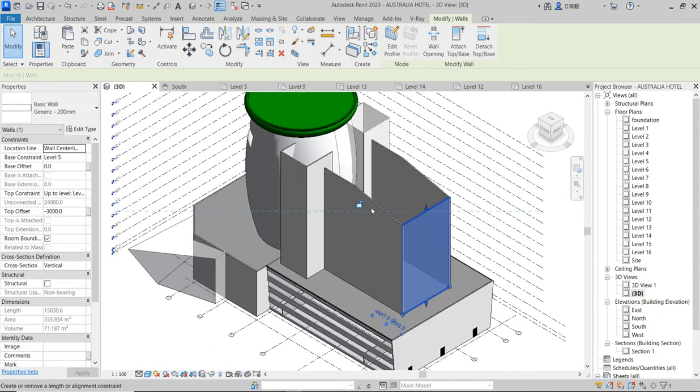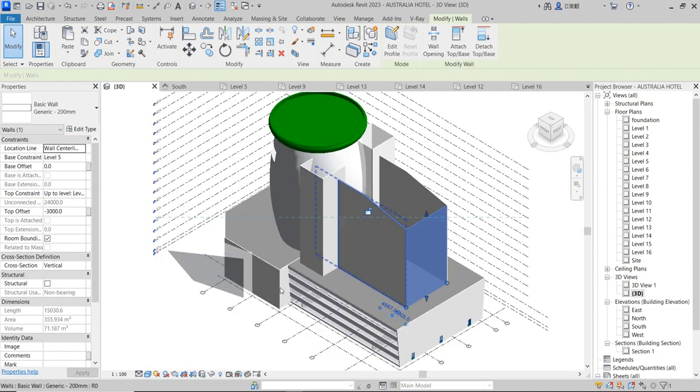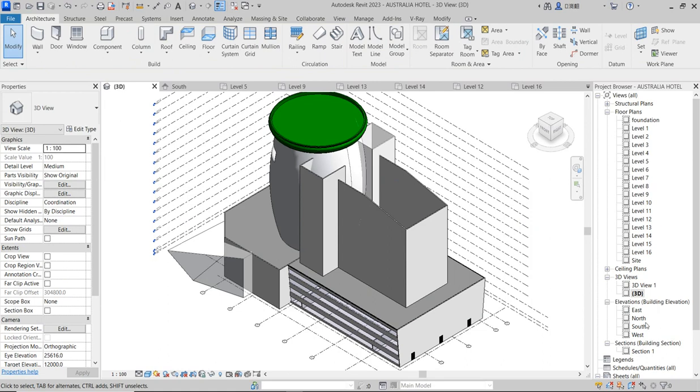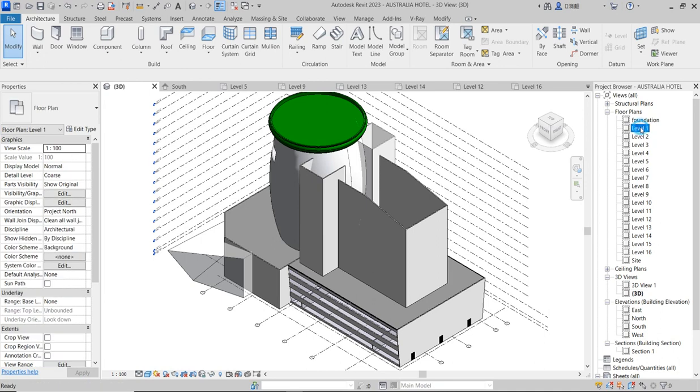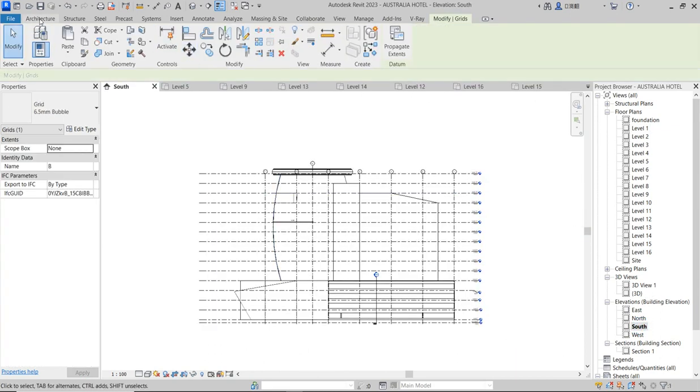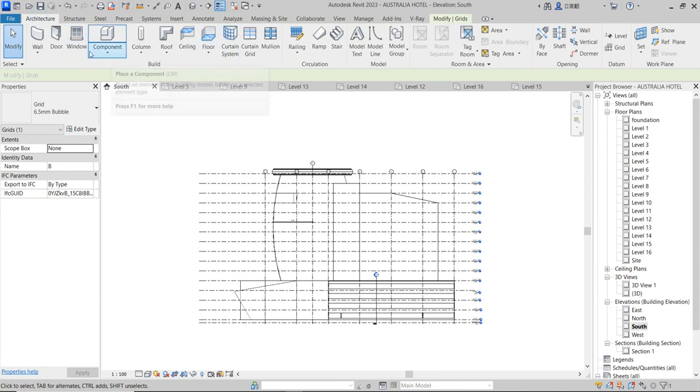So the next thing is that we want to create another useful concept here, which is going to be a ribbon concept. So what we do is that we go to West Elevation and we go to know what you are going to use. You are going to use this grid, grid C. There is grid B. So go to start elevation and you come to architecture. From the architecture you say model in place. No, not model in place. Okay, let's use just normal roof by extrusion.